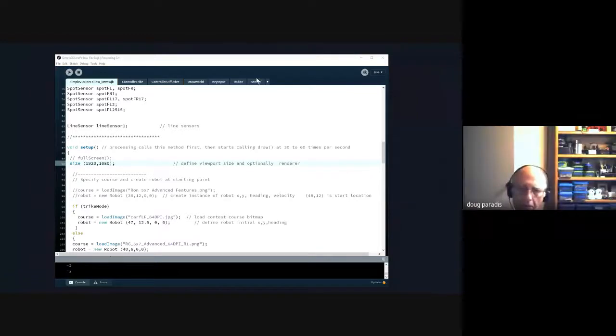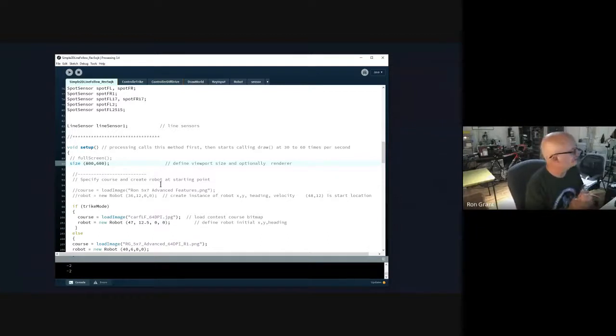Hey, Ron. Yes. I do have a question. I saw when you were looking at your controller that Will seems to have the wheelbase in his. Obviously, that would be an important thing in the differential robot too, but I didn't see it in yours. Oh, it actually doesn't matter in this case, because we're not concerned about individual wheel velocities.